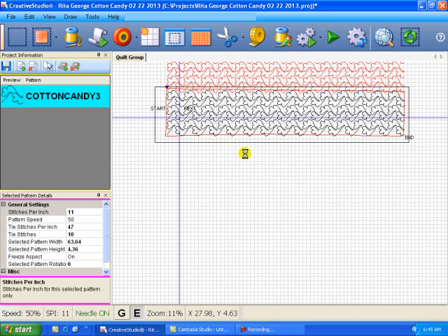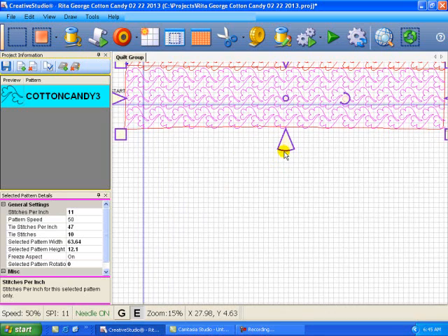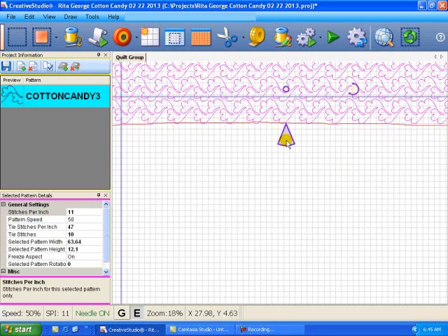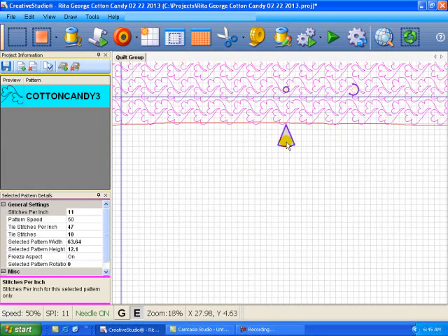You should not have a situation where you do not have enough pattern, or you have too much pattern at the end. So I'm going to make this very small adjustment by using the center bottom wedge, and I'm just going to raise this up just a tiny bit. If it comes down right to the line, that's fine.